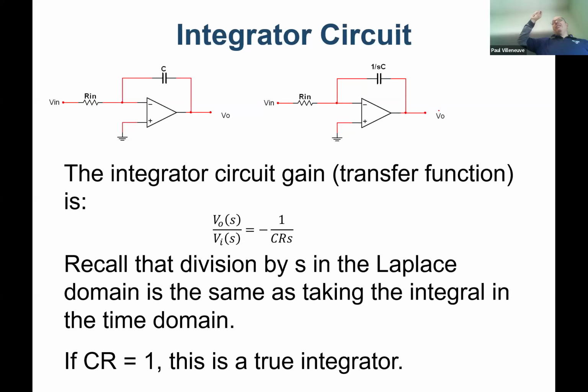When you have an orifice in there, it takes the pressure that's behind, that's jacked up, and on the other side, the pressure drops. Yep, because you're letting less water through, just like the case of voltage. But if it oscillates, it's still going to oscillate a little bit below the orifice too, just like it would after the resistor. Here's the interesting thing about an orifice. Anytime you have something that drops the pressure, that has to take energy out of the system, which means it generates heat. So if you go to a pressure reducing valve, which is the most common one you see, and it's just got water going through it, you put your hand on it, it's actually pretty warm.